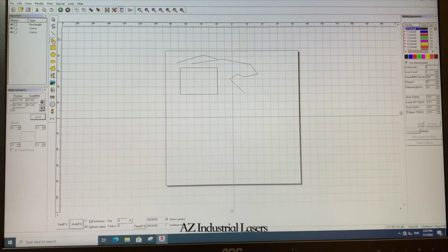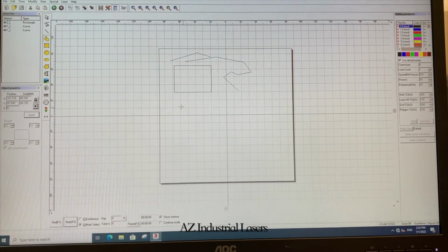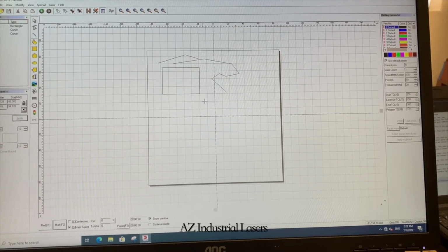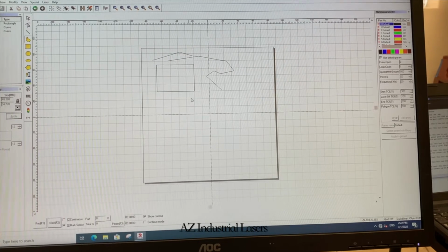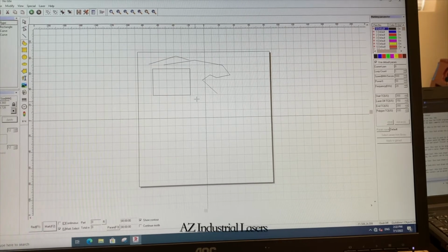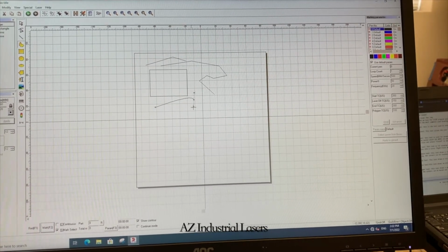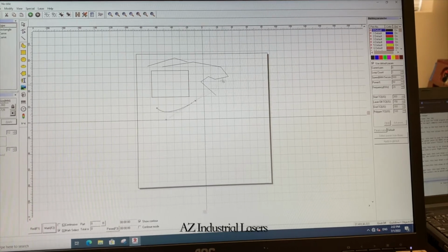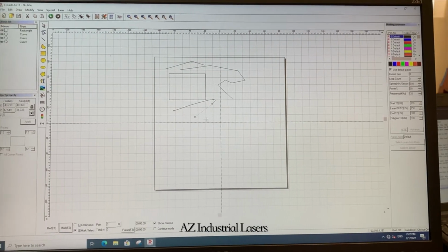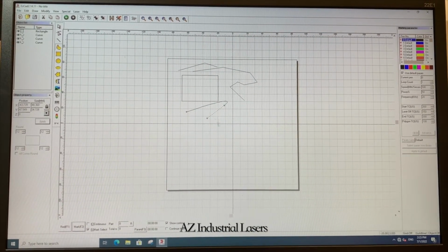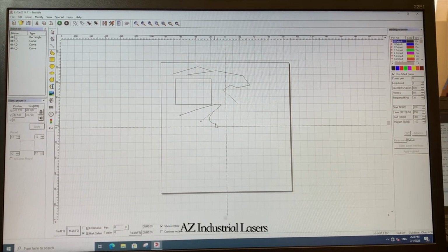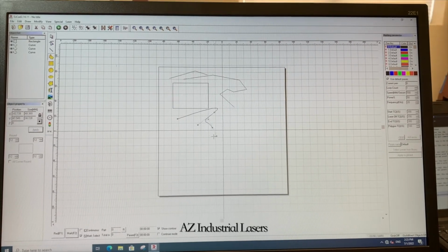And similarly to the line tool, we have the curve tool, which, just like the line tool, where you click it once, it places a start point. And then wherever you click it again is going to be the direction of the curve, where the back end of the curve is. So if I click over here, click and drag, you want to click and hold the second time with the curve tool, and then it'll pull the line into the curve. And then wherever you let go of this is where it's going to place the next curve, and then wherever you click is where the point is going to be. So if I click here, the curve is going to follow this line and then make its way to the point that I place. And if I keep on holding it and move it around, it can further alter it.